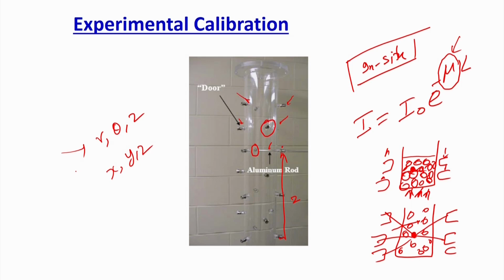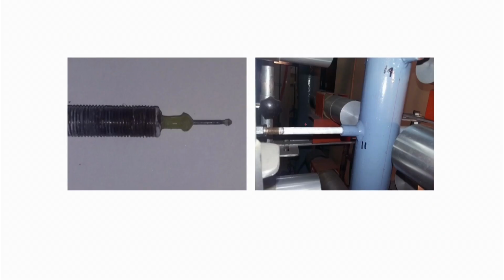I have taken the photograph at an empty column so that we can explain the facts. Suppose this is the opaque column. We take this kind of a threaded rod, and if you see this figure, we put the tracer particle on the top. This is my tracer particle. At the in situ condition, we place the tracer particle through these ports, and the detectors placed around actually record the counts. Definitely these detectors are going to record very high counts compared to the other detectors which are placed here. So for the calibration, if I put it here, I will get the count recorded on each detector for this location of the tracer particle.